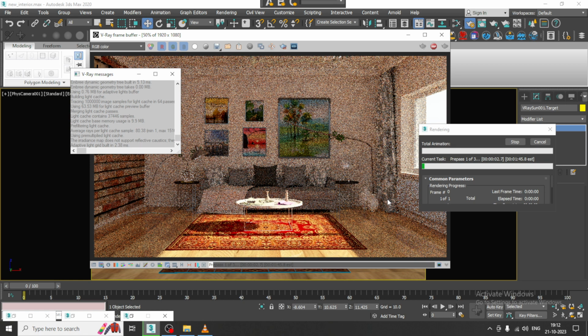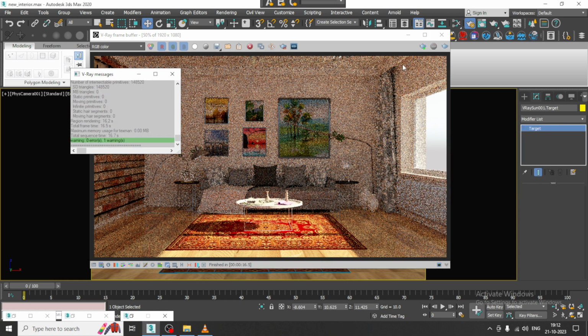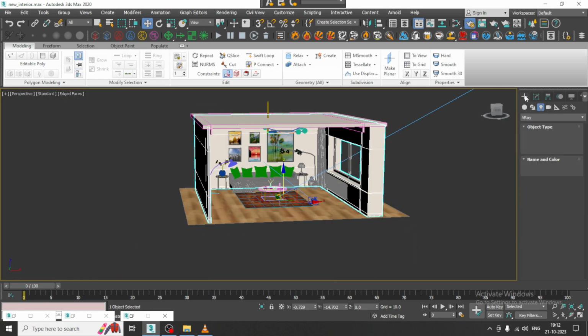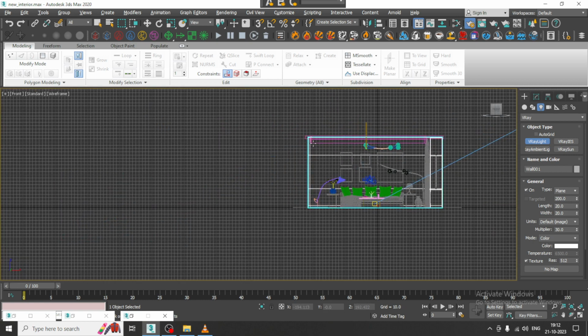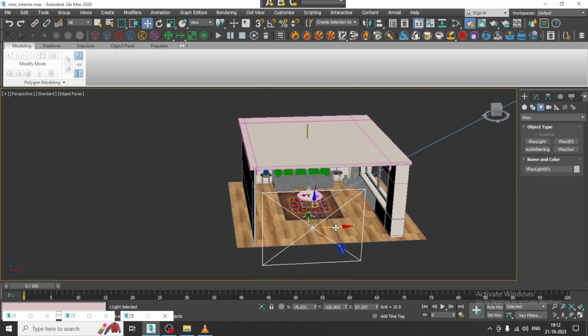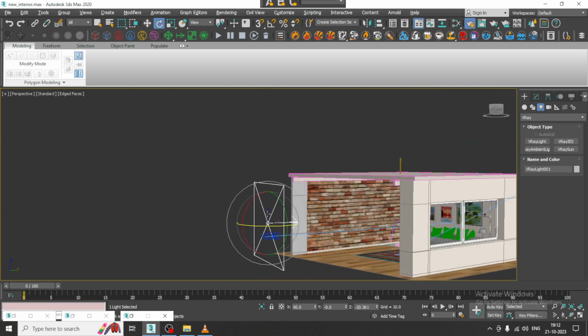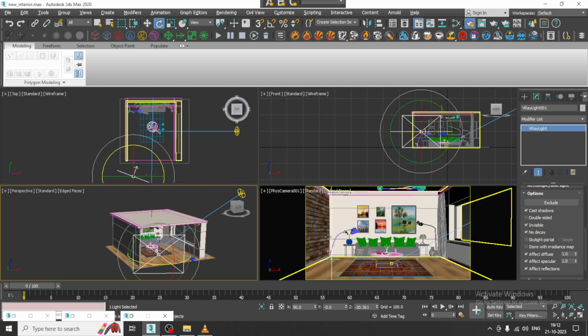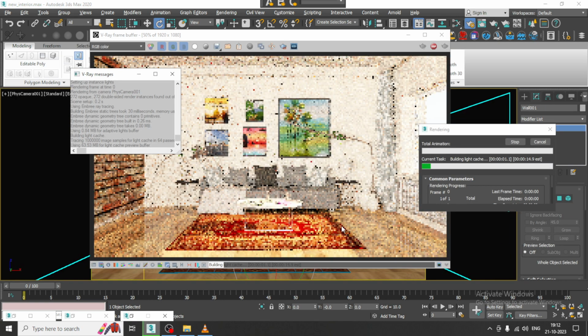All right. So we can add one more Vray light right from this direction, a kind of fill light. I'll select this and drag it over here, and let's set the temperature. Multiplier as 2 over here. Go into the options: double sided, invisible. If you don't need it, you can just turn off that double sided.